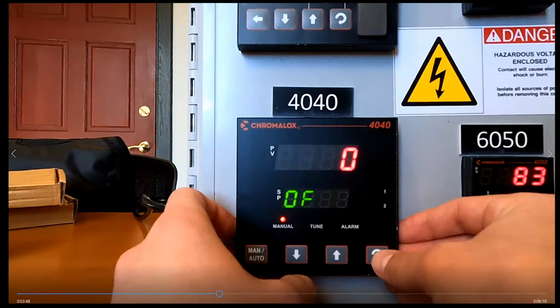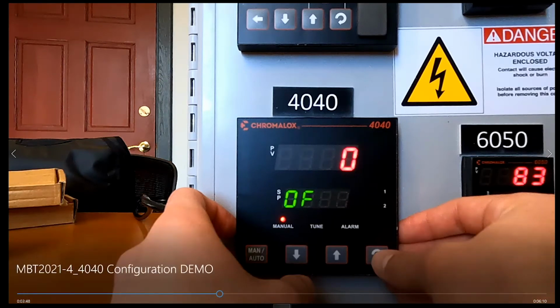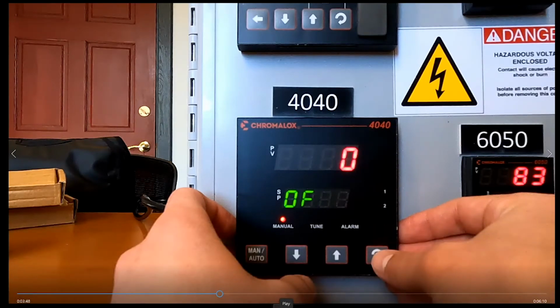If there's really no way to get around that differential, you can use this offset feature to artificially change the variable that the sensor is giving. So you can artificially adjust the temperatures to make sure that you're getting where you need to be, even if you can't measure the exact part of the process that you want to.